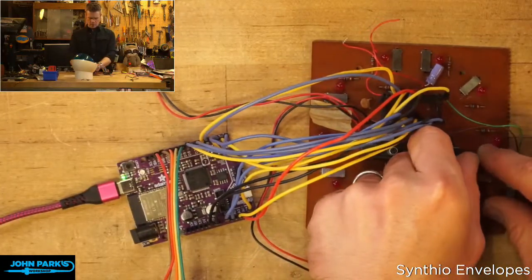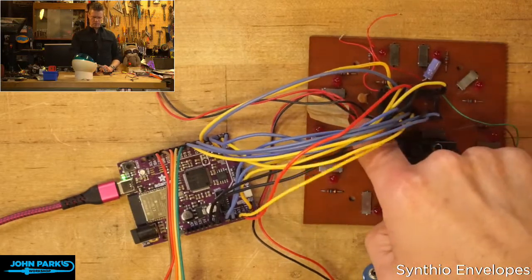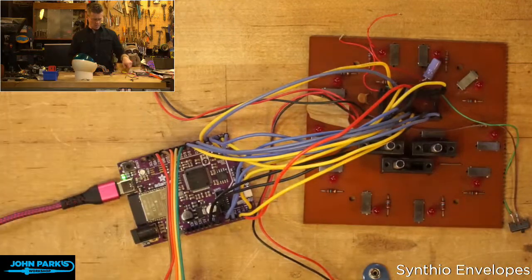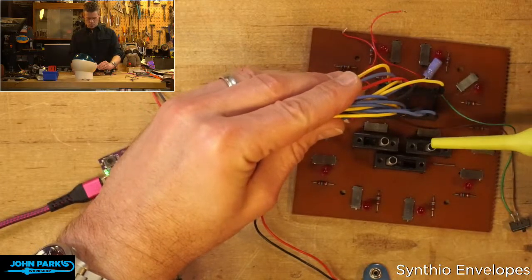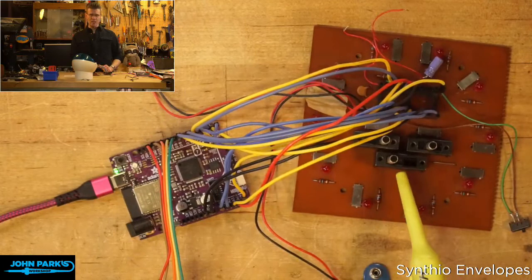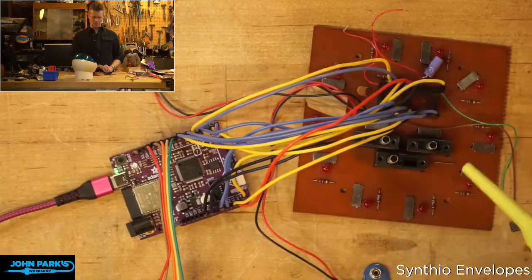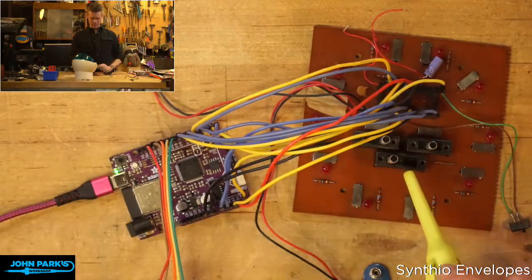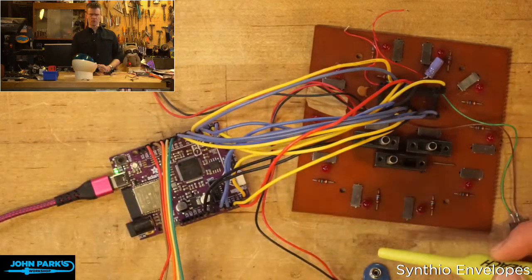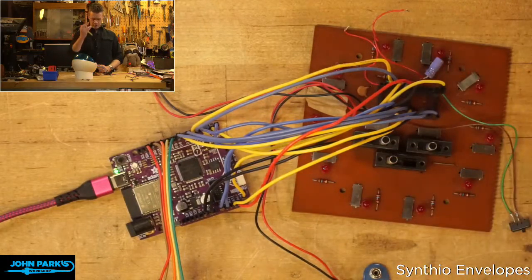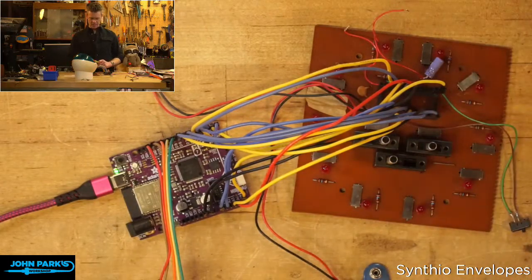And I can't remember, do I have this one do anything? No, I think that one was doing hold before, and I took that away because I realized hold made more sense there. So I've essentially got free for use in designing this one momentary switch here and one toggle switch here. This toggle switch I can't use because it's a complicated matrix of these guys, and I'm not reading it the way the original chip was, scanning those like a matrix. I'm keeping things simple, so I won't be using that one unless I cut the traces and use it for something else. But so far, this is essentially a non-destructive edit that I'm doing on this circuit board, so I might try to leave things intact.